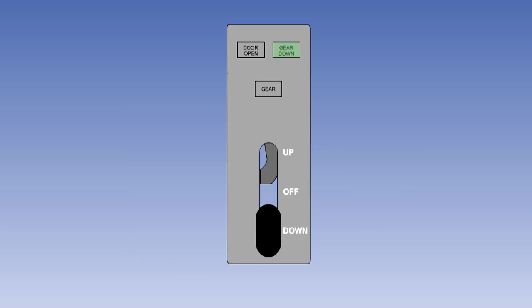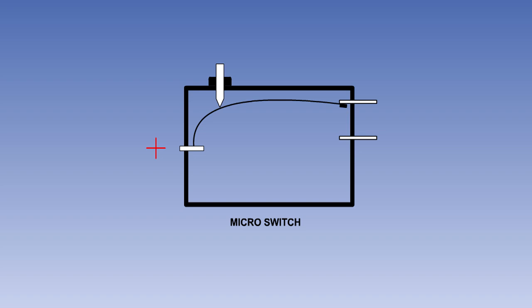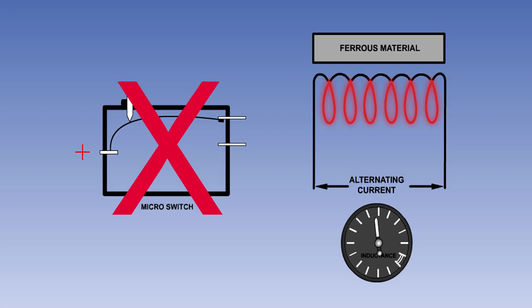It is important on aircraft with retractable landing gear systems that the pilot is kept informed of the position of the landing gear. On older aircraft, this is achieved by using gear-operated microswitches to operate indicating lights. On modern aircraft landing gear, inductive-type proximity sensors are used instead of microswitches. In a typical undercarriage system, each proximity sensing unit will consist of three components.